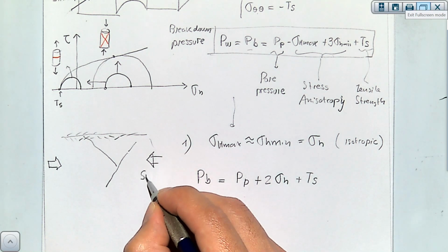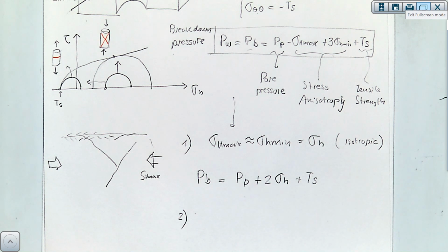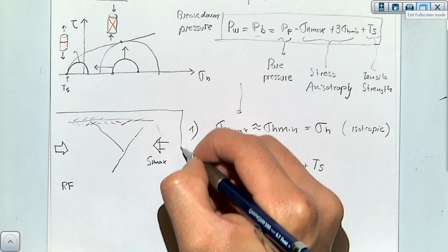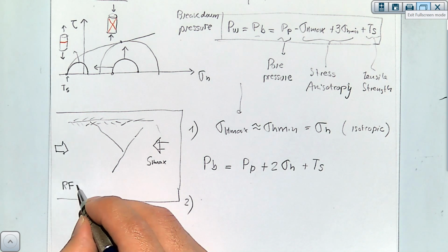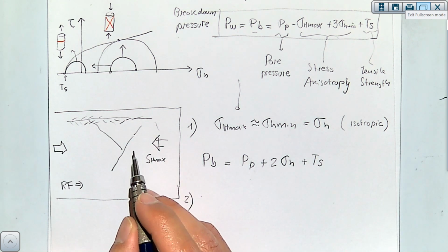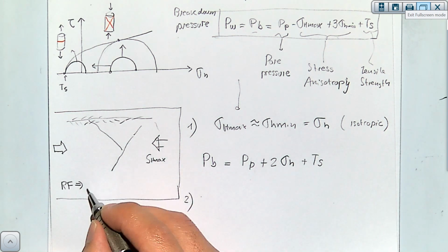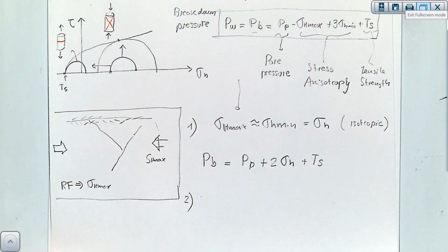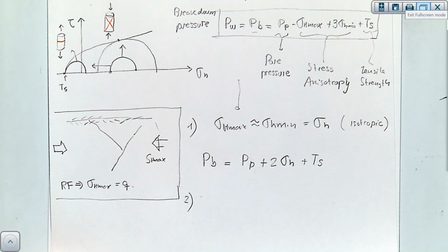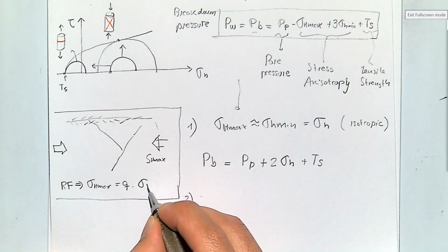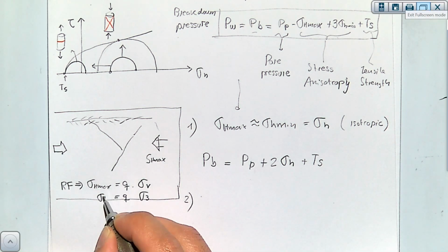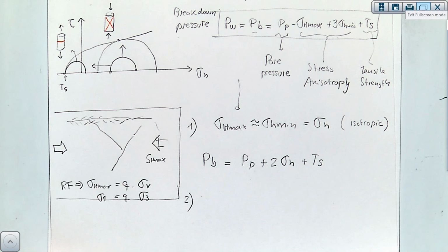And for example, if I have a reverse stress regime, what the equilibrium of failure or the equilibrium of fault would tell me is that the maximum stress is limited by friction for reverse faulting.